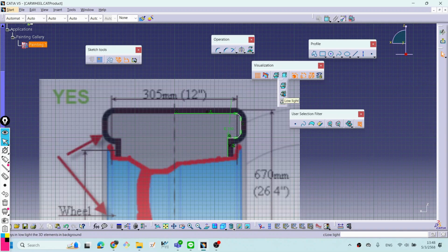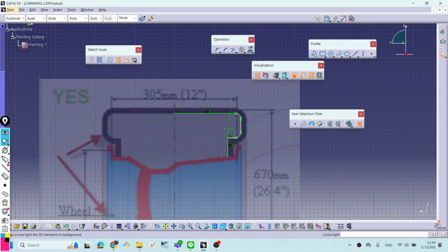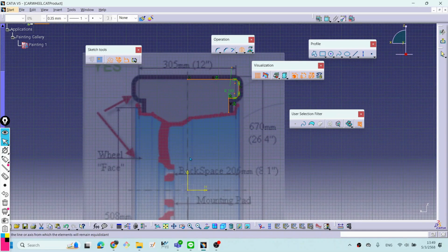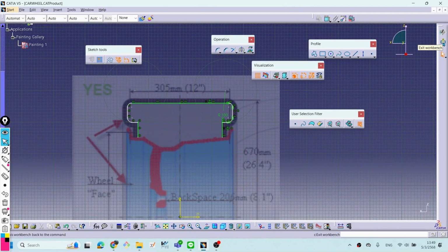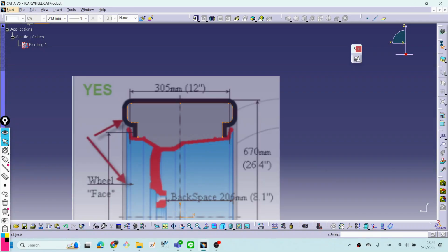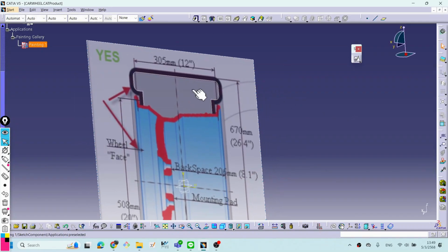You drop down to the second command, right? Okay, you focus on the current sketch already right now, right? Current sketch, right? Okay, easy to select already, right? And select on command symmetry and select the mirror axis, right? Right here, completed, done, right? Okay, I just go out of the sketcher module already, right here.